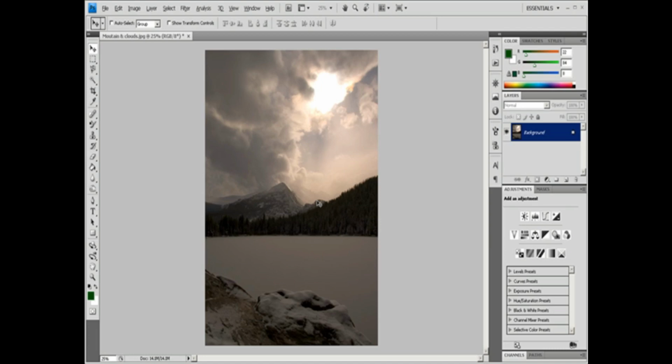To use the Clone Stamp tool, you set a sampling point on the area you want to copy or clone the pixels from and paint over another area. To paint with the most current sampling point, whenever you stop and resume painting, select the Aligned option. Deselect the Aligned option to paint starting from the initial sampling point, no matter how many times you stop and resume painting.